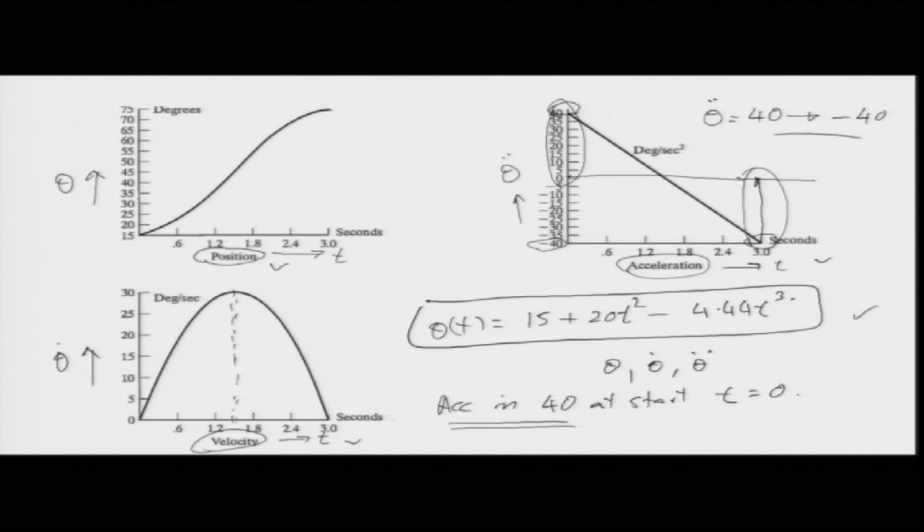So, in this we are going to start very slowly. Let me draw it here again. Why very slowly? So that the acceleration will pick up slowly when the motor is taking time to accelerate. So, I am going to have a parabolic start like this. It is going to start very slowly from here, then it will become a straight line, then it will stop very slowly there. So, here and here we are going to have a parabolic blend, and here it is more or less going to be a straight line.